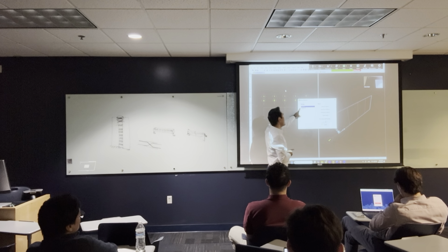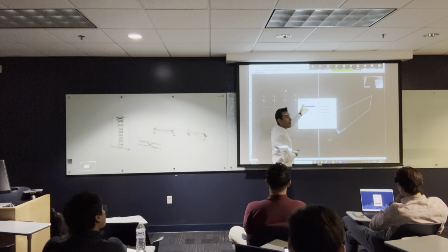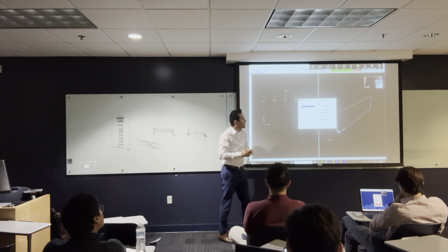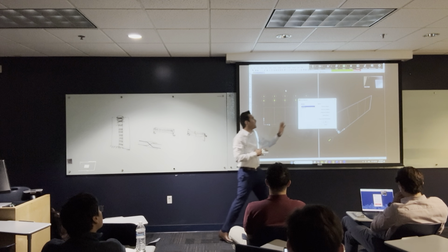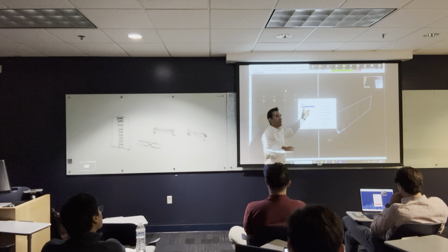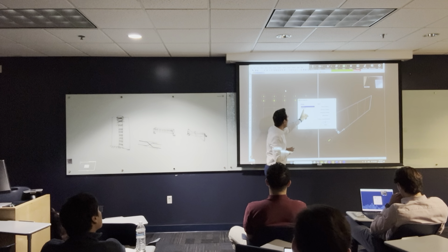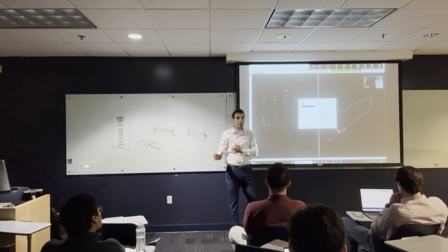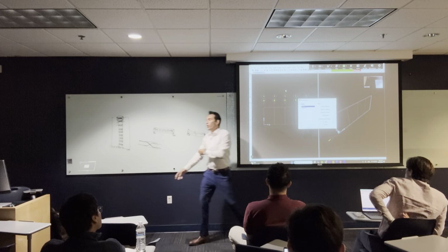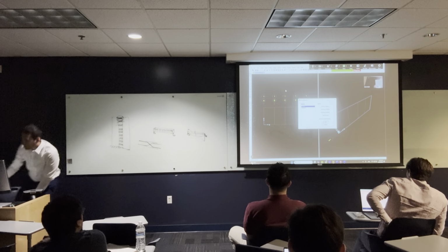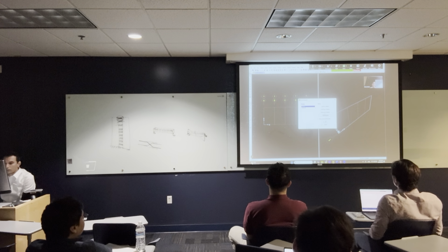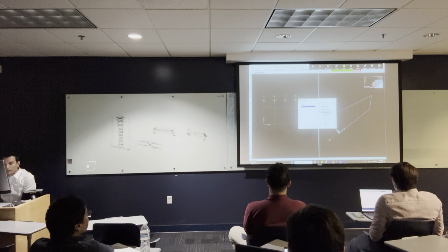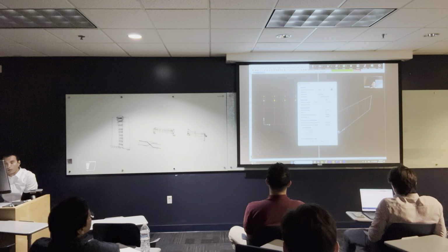Okay, so let's go into this material and see what it has. From the name, I can see it's about 4,000 pounds per square inch, which gives me the vibe that this is a concrete. This one says A992 Fy 50, which means, oh, sounds like a steel. If you want, you can modify this material. So I'm going to say modify and show material. When I click on this, all this is going to show up.